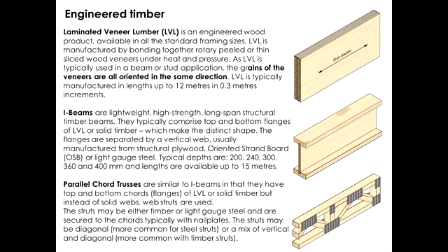I think that in both of your case studies, you've got the parallel chord trusses. I believe that's your case. So again, we're talking about top and bottom chords which are made of LVL. And what they're called here, the web struts, so those diagonal elements, they're not really struts. I would call them bars, because strut means that the element is in compression. They're not necessarily working in compression. So bars,